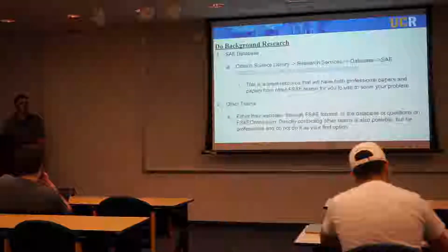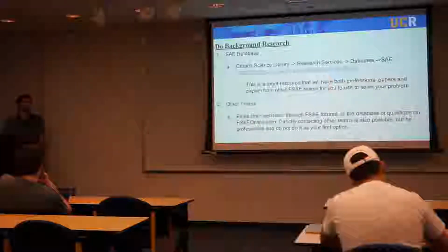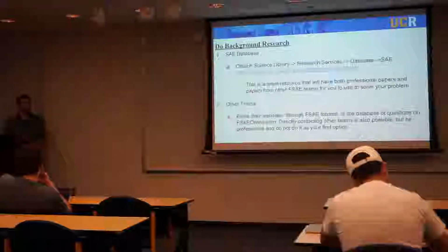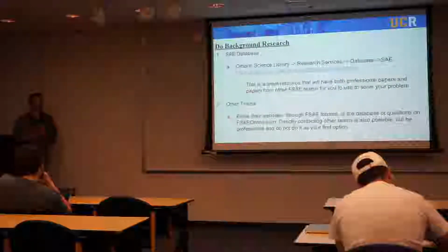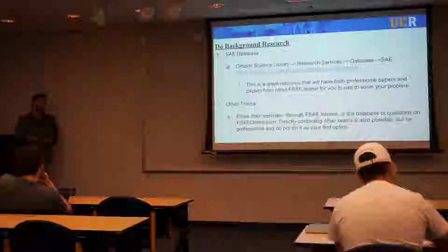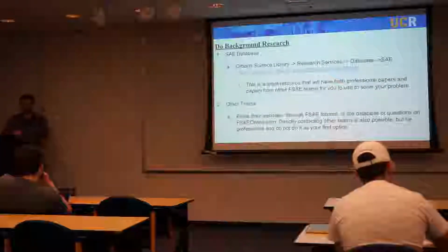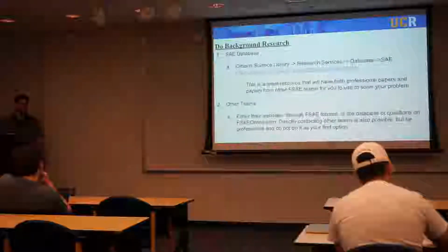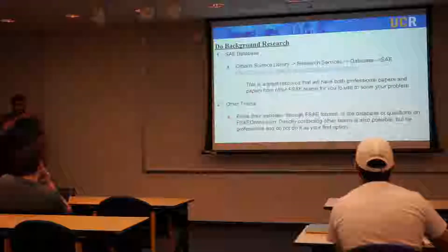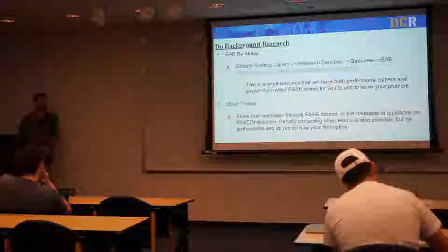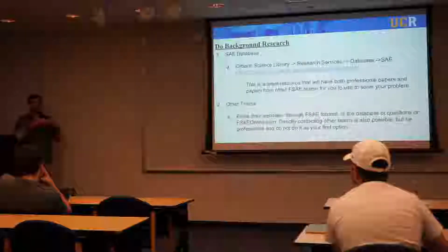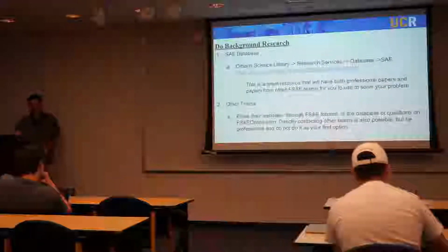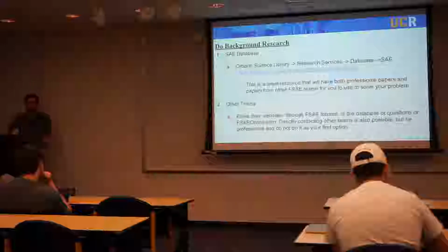I didn't really know how to calculate the flow that was going to go through that. Some people define it as a restrictor, and you might be able to use some physics forms to define that. But what really helped me a lot was this SAE database. It won't pop up on your Google searches. These papers aren't just going to show up as the second option on Google. You have to go to the database.